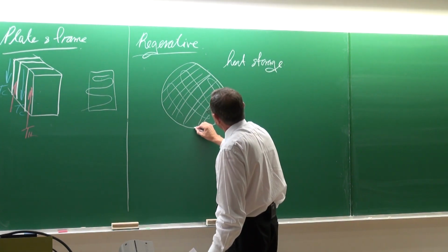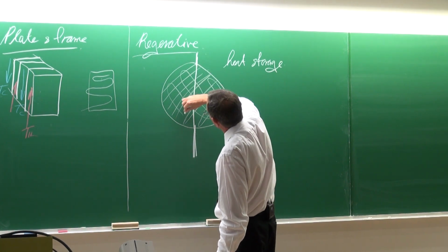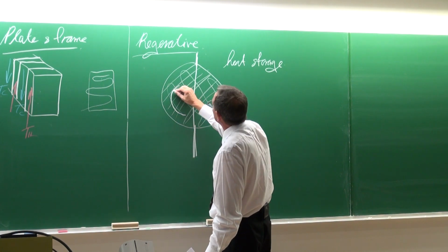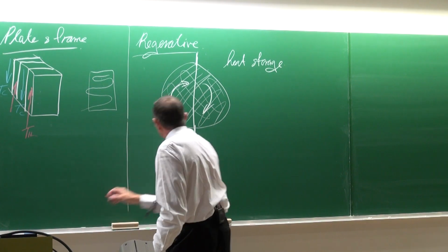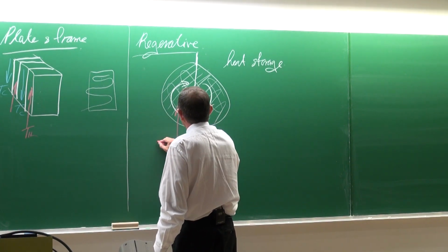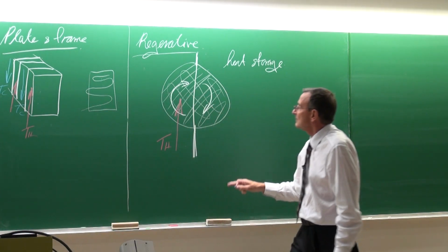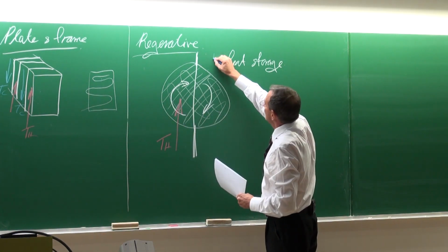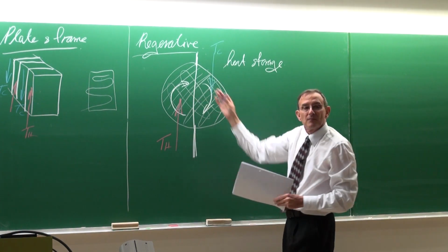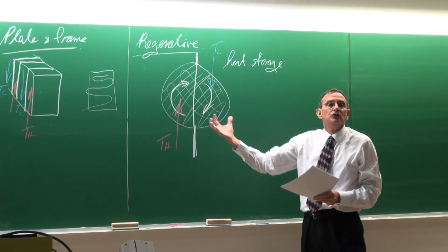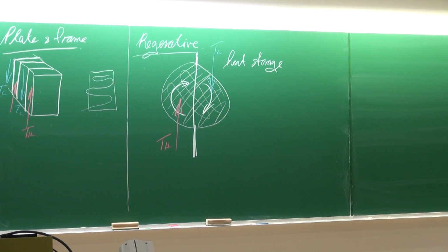And in principle what you do is you separate the one stream from the other stream like that. This would rotate like that, and then you're going to have the hot stream that would heat this big porous body, and as it then moves around, you will have the cold stream that will be exposed to the hot body, and that is how the heat transfer occurs.